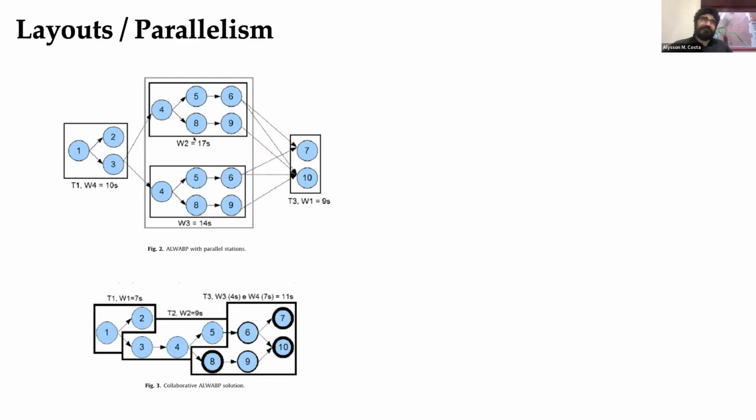The interesting aspect in this problem was to compute the actual equivalent cycle time here. So when you first approach it, the way we just thought, oh, that's simple, it's just the average of the cycle times, but that's actually wrong. So in order to compute the equivalent cycle time for these two stations, you actually need to do something like you do in electrical circuits. So the resistance is actually the 1 over the cycle time, the equivalent cycle time is equal to 1 over the first cycle time plus 1 over the second cycle time. And of course, this is not linear.